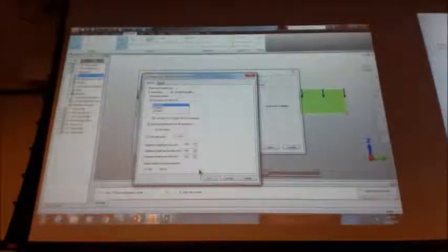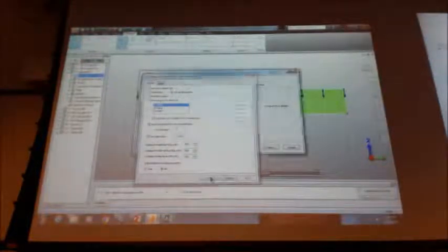If you do your own CAD drawing, draw things on layer 1, 2, 3, 4, 5, whatever. Don't use layer 0. If you do it on layer 0, it brings it in as 255. And if you make the layers colored, then it associates that with the layer. When we have a part, layer, and surface, it'll associate it with that. I can't remember exactly what, but you can look it up in the help. But you have to set these settings before you bring your file in, otherwise it just won't work.